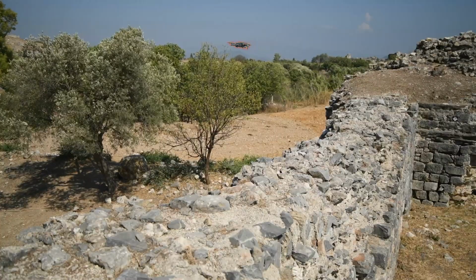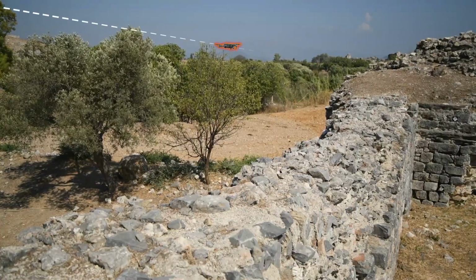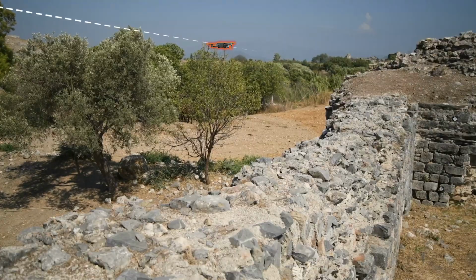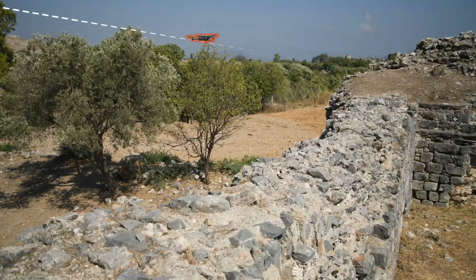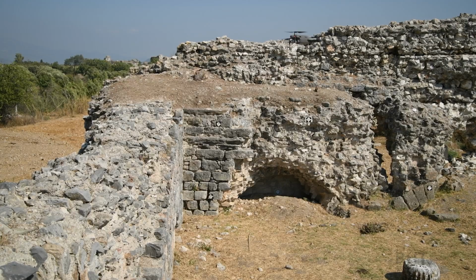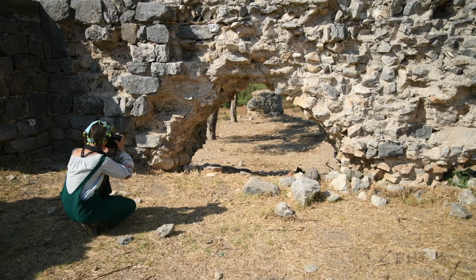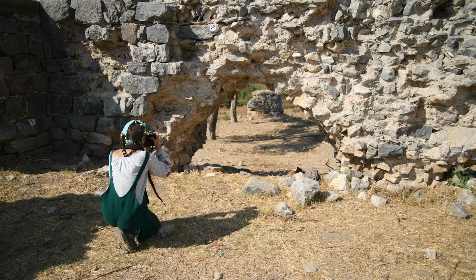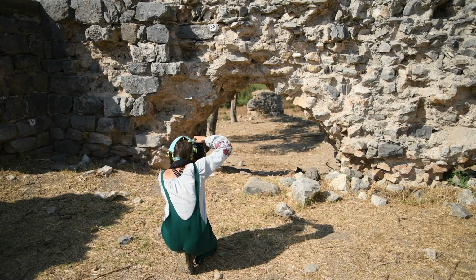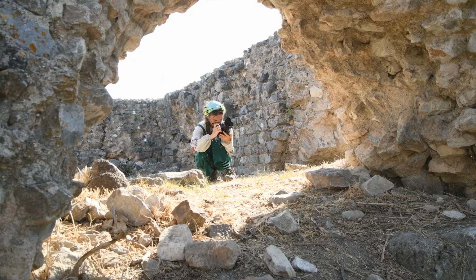To take pictures from even higher up, we use a drone in the example of our object. As there is a different camera mounted on the drone, different parameters naturally apply to these images. Pixel size and shooting distance are also calculated in advance here. For the systematic sequence of recording, it is also advisable to proceed line by line. If the object has special features, such as arches, holes or niches, it makes sense to record them independently after the systematic images have been taken.